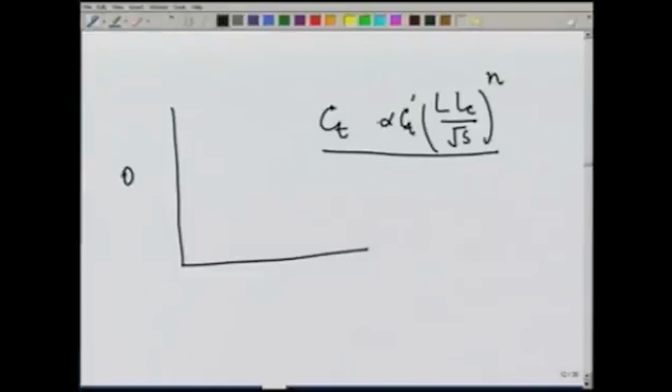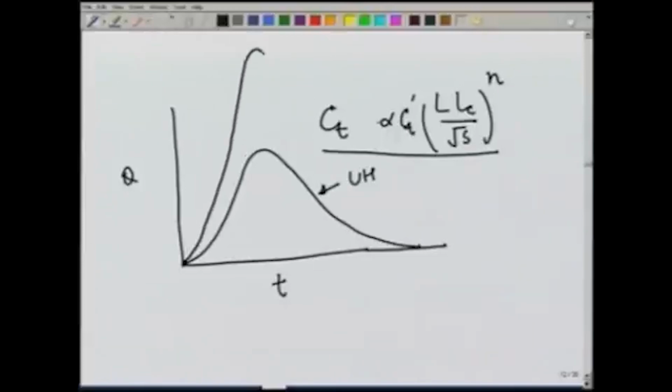Now, synthetic unit hydrograph or instantaneous unit hydrograph or a regular unit hydrograph, these all give us how the discharge varies with time. Based on these UH, we can derive the DRH. For example, if we know the depth of rain is 1.5 centimeters, we can derive a DRH which will have everywhere ordinates equal to 1.5 times the UH ordinate, and once we get the DRH, we can add the base flow and get the total runoff hydrograph, which would look like this.